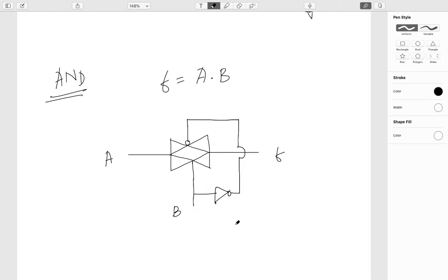So it's very easy to do the AND function. If I want to get this high, VDD, then this should also be VDD, because then this PMOS will be on, and of course I need to apply the negative, so B bar will come here. We know that control and control bar.